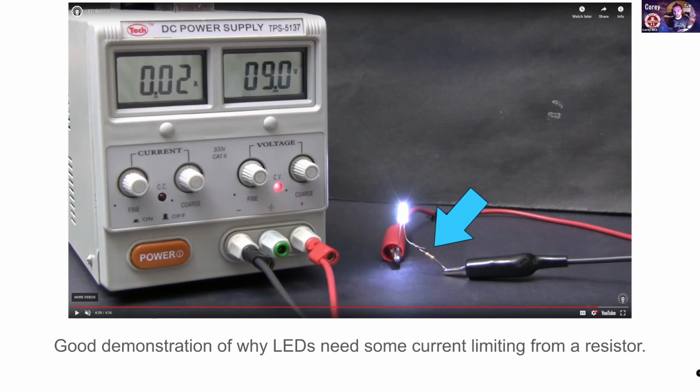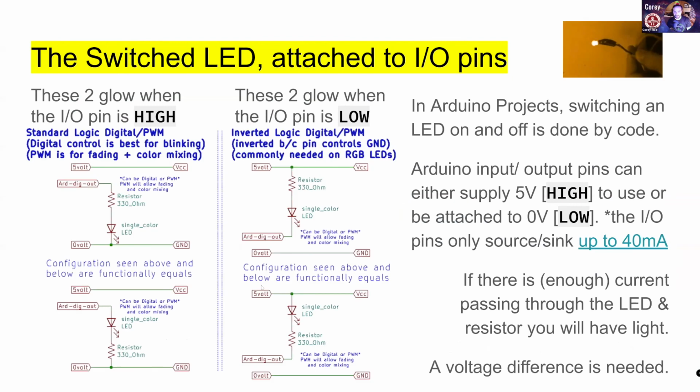Having a little jig so you can check which way is forward on an LED can be really helpful. And it doesn't need to be soldered in place or even a breadboard. You can just touch it to contacts so that you can see what's going on. It's a good trick if you feel like you're losing your mind with LEDs, which can sometimes happen. I'm going to warn you in advance. They're just fiddly, and their failure modes can be so subtle, like that one that just blinked off.